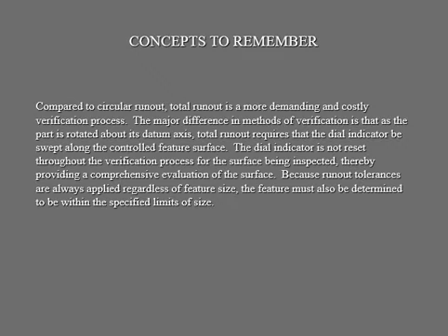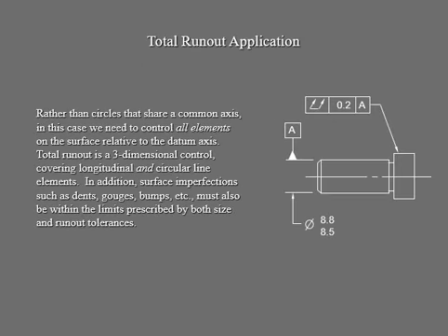So let's take a look at that. We don't need it, just read that. We will go into all the total runout application. We don't have to say this because it's about the same thing. You will have your axis, you will have your datum feature, this one is a smaller diameter for that surface, and then of course your total runout is on a bigger diameter, sharing the same axis right there. So you should know how to read these by now. Total runout 0.2.